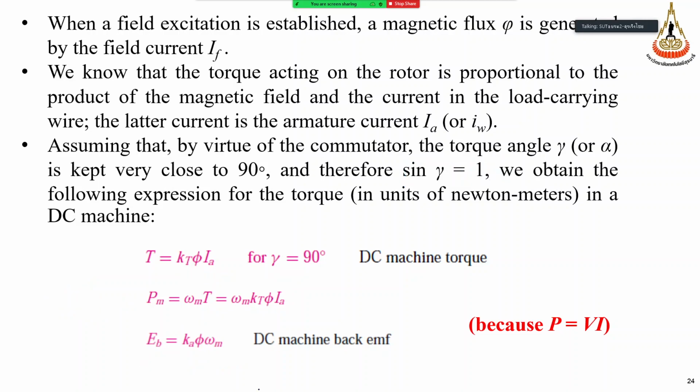For a generator, if you use the DC machine as a generator and drive it with higher speed, the voltage increases. You measure the voltage in the laboratory. So when you go for laboratory next term, I suggest you come back to see this equation, that will give you more idea about the DC machine. On the other hand, for a motor, if you drive it with a higher voltage, the speed will be higher. It depends on the constant value and the excitation flux of this machine.